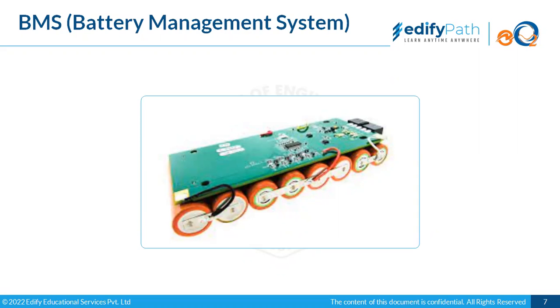So what would the BMS say about the lower voltage we have discussed? If it is an NMC cell with a nominal 3.6 volts, the lower end voltage would be around 2.8 volts. If one module is discharging fast and reaches 2.8 volts earlier, the BMS would consider the battery fully discharged. In that case, the charge left in other modules will not be utilized, and the battery would give a lower range than it normally should.